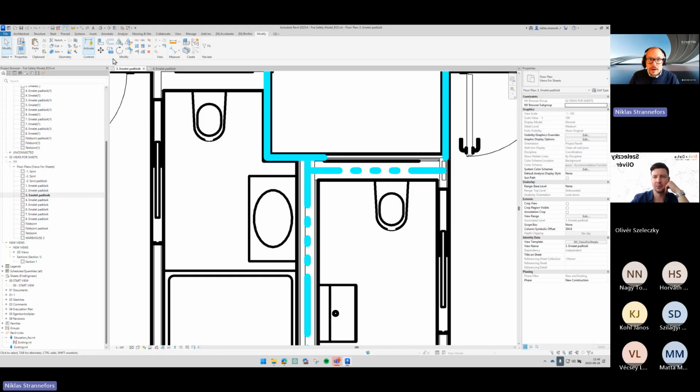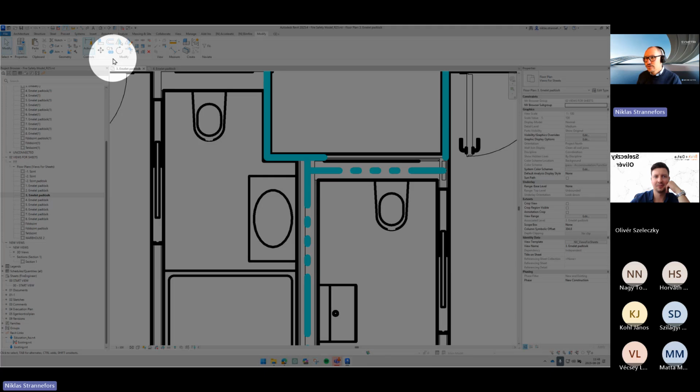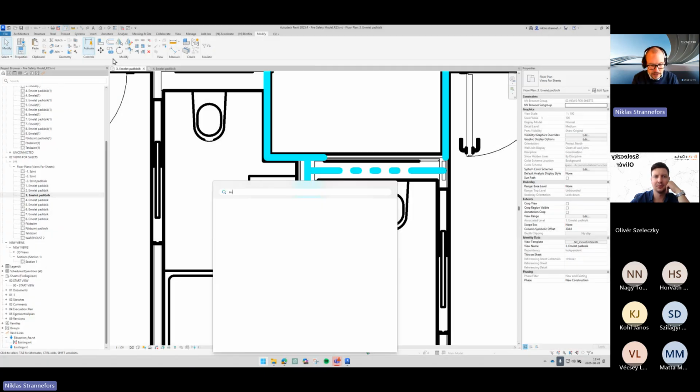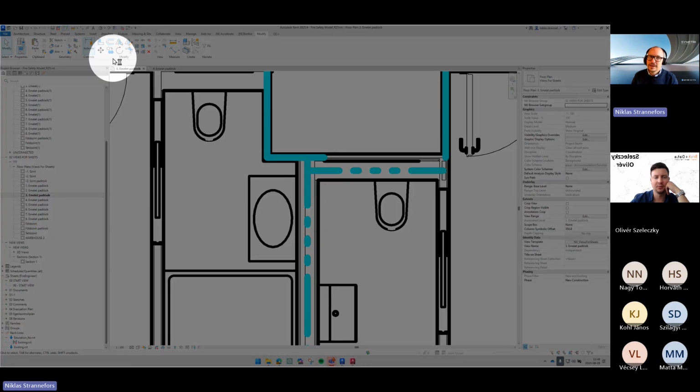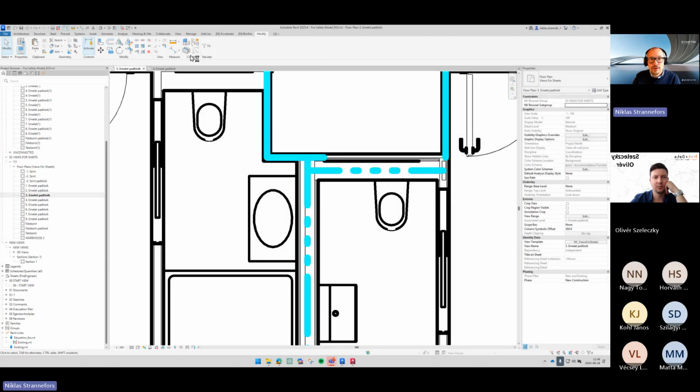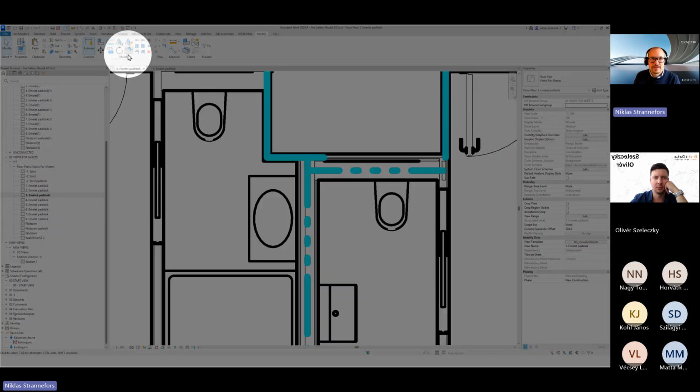Yeah, I see nodding. Revit has the same features as AutoCAD does. I can open it as well, so you can see it. These Modify tabs are the same in AutoCAD as in Revit, they do the same. But Autodesk, creators of Revit and AutoCAD, decided that in Revit they work exactly reversed compared to AutoCAD. So, for instance, go to the Modify tab, go to the one called Trim Corner. It's to the right of the rotating symbol.